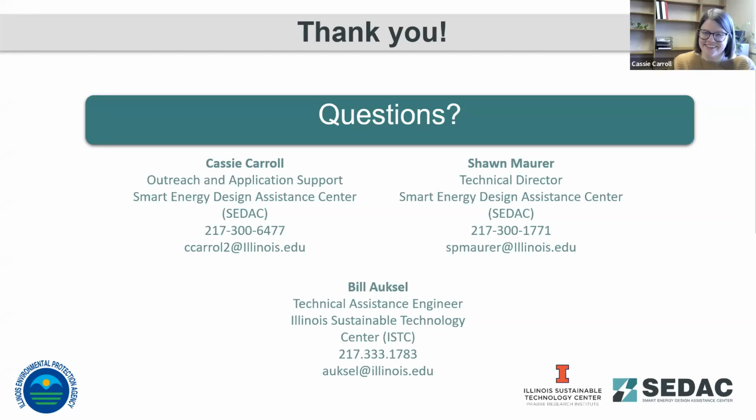And Sean, you want to chime in? Yeah, I do know that 10 horsepower and 2,000 hour operating limit is kind of the standard for HVAC type pumping systems and low head recirculating type systems, things like that. When you start looking at higher lift systems, maybe you want to have a 20 horsepower, 25 horsepower motor for that payback to be there, just because you don't have as much turn down capability in a higher head system. So that 10 horsepower, 7.5 horsepower, somewhere in there, and 2,000 hours is really good for HVAC systems and recirculating type systems as a rule of thumb.